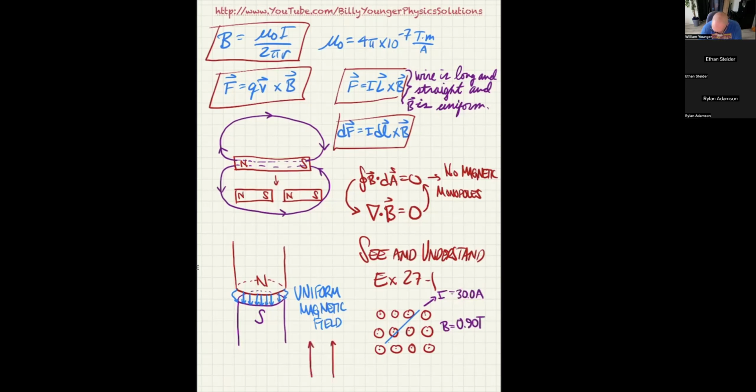Here are your magnetic field lines. And then you could imagine the wire in this case being oriented like this, and this angle right here would be 60 degrees. And this right here would be the current I. So then F would be, we use F equals BIL, and then of course you'd have to say sine 60 degrees. So that's meant to be F equals BIL.